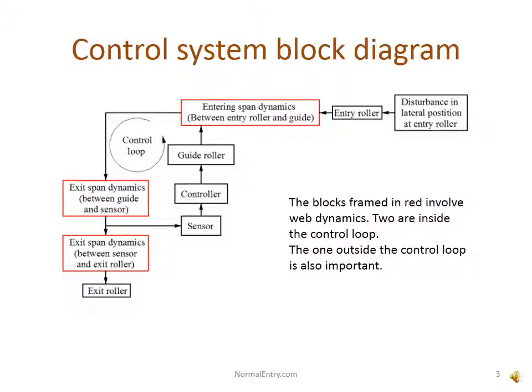There are delays in all of these blocks, and delays cause problems for control systems. Sensors and controllers are rarely an issue, but actuators unavoidably contribute a significant delay. For example, converting the rotational velocity of a motor to lateral position takes time. Control engineers call this integration delay. By itself, integration delay in the actuator doesn't prevent high-performance control, but it doesn't leave much room for delays caused by the web.